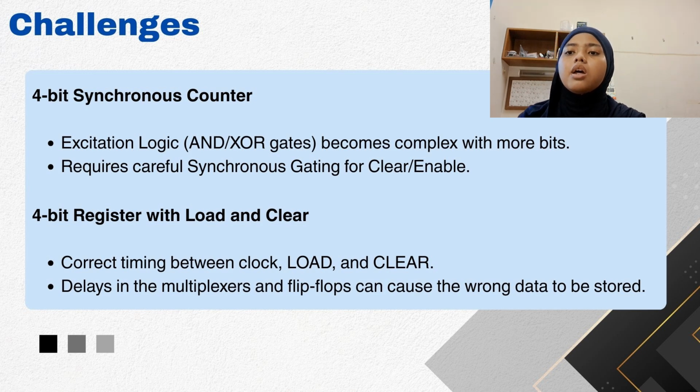Excitation logic and XOR gates become complex with more bits. It requires careful synchronous gating for clear or enable. Challenges for the 4-bit register with load and clear: correct timing between clock, load and clear. Delays in the multiplexers and flip-flops can cause the wrong data to be stored.